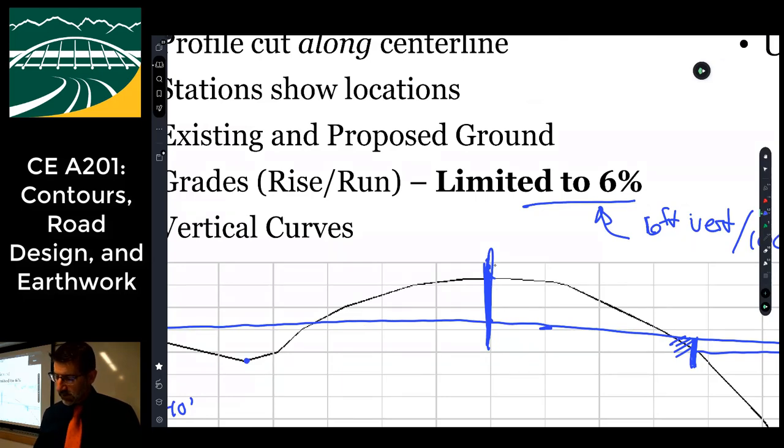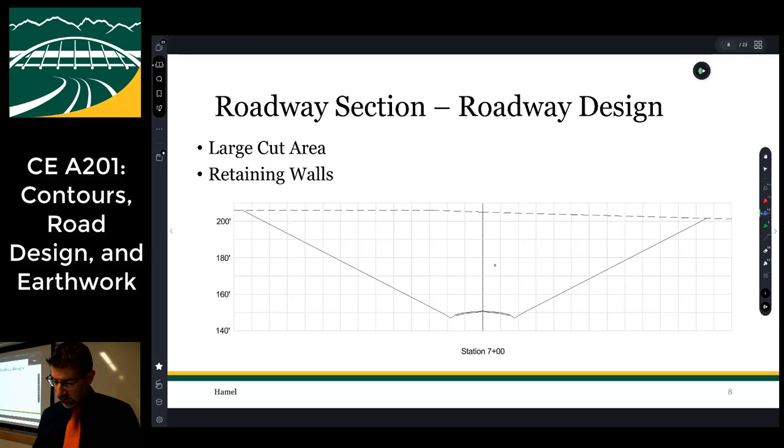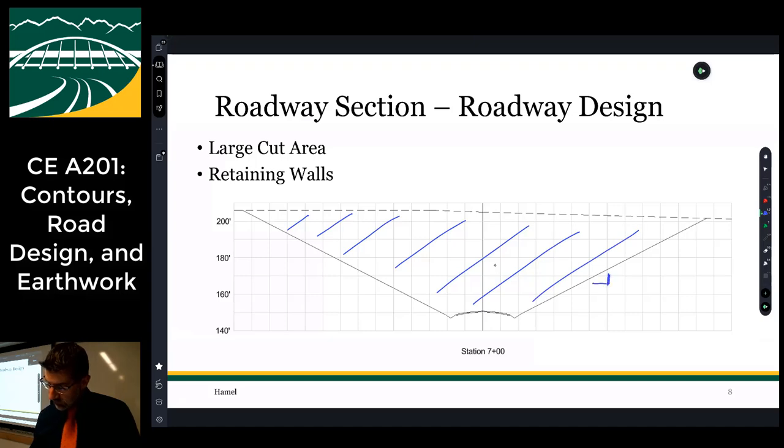And so the only way to make that work is to cut all that land out, right? And so that's going to look like this. There's my existing ground, kind of falling off to the right, but I have to come through here with an excavator. First of all, I have to define this slope, which is typically 2 to 1. Why not steeper than 2 to 1? Why don't I do a slope like this? It'd be way less work.